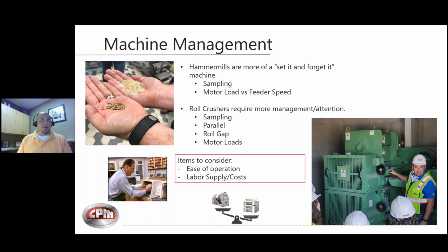Roll crushers, we really want to make sure you're managing that properly. You're taking samples, and not only just one sample. With roll crushers, you almost want to take one on each side of the machine, both the left side and the right side, and then you can take them on every bank of rolls you have. You don't have to do this every hour, but it is something I encourage just to make sure that machine is running properly. So we do see roll crushers, we've talked a lot about benefits earlier. This is one of the more disadvantages: it does take some additional management or even attention from some employees.